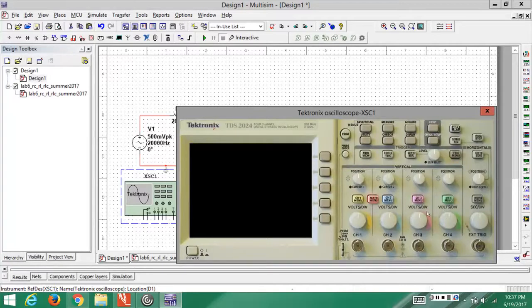And what we usually do, the simplest thing to try, is once you set up your oscilloscope with a probe here, and you connect it to your circuit, and you know that you're receiving some sort of signal or reading in your oscilloscope, we try this auto set button over here, and that calibrates the oscilloscope by itself and then shows you whatever waveform it is picking up, and we get to measure the voltage or the time from the x-axis from that waveform here on this black screen.